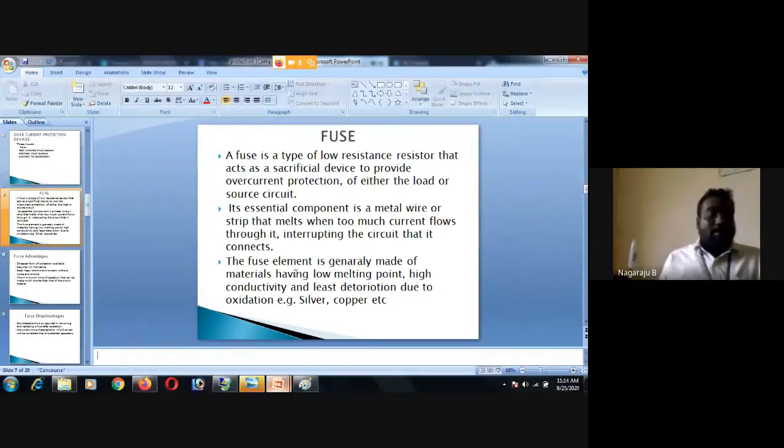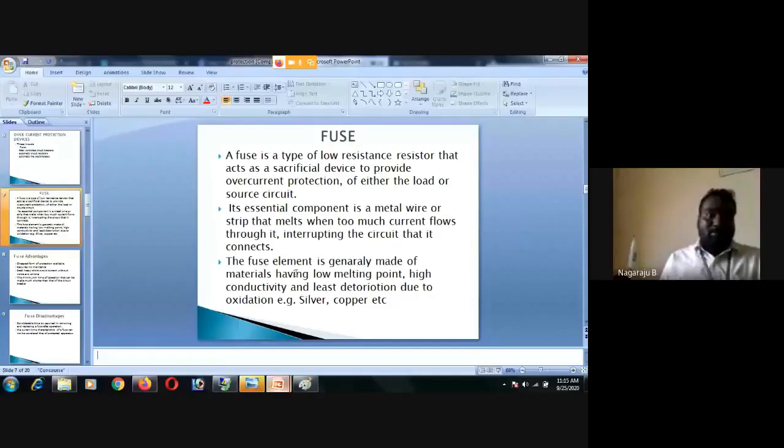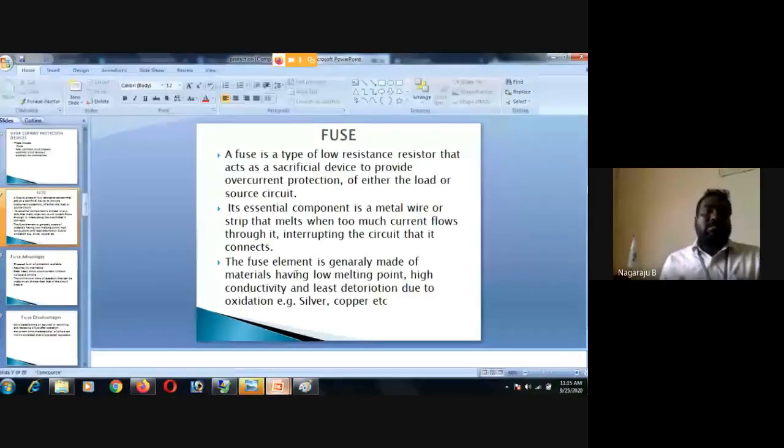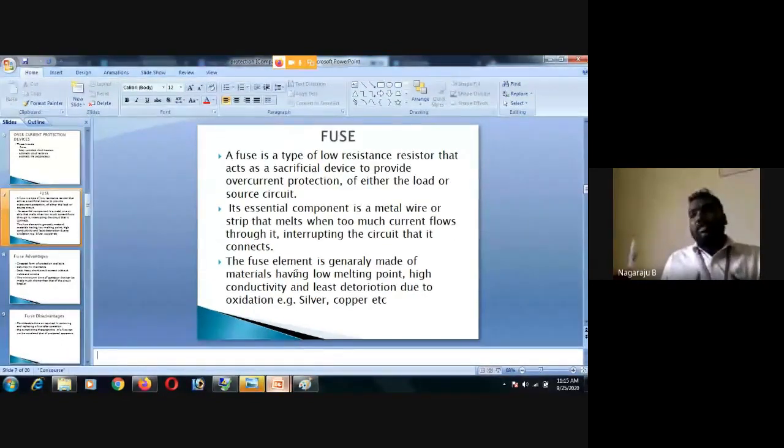Always remember these fuse cutouts. These fuse cutouts are the most common type of protecting device. These power fuses are mainly used for the primary distribution system, which has 11 kV of power, so you need to use a higher rating. So you can have two names, fuse cutouts or power fuses. You need to know about this.